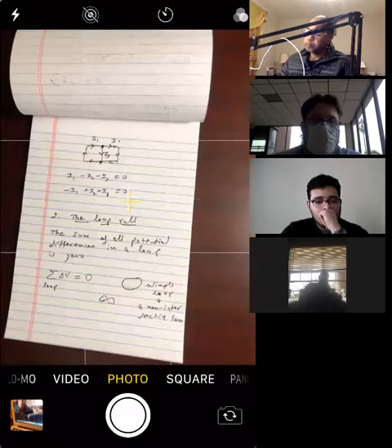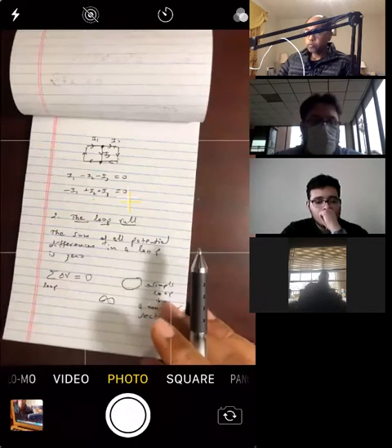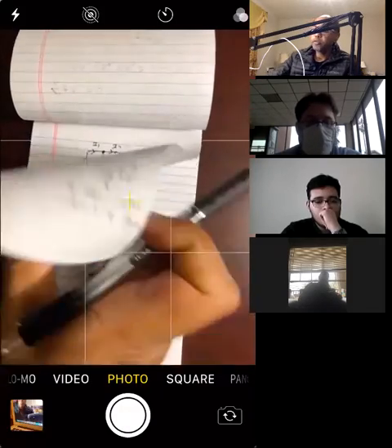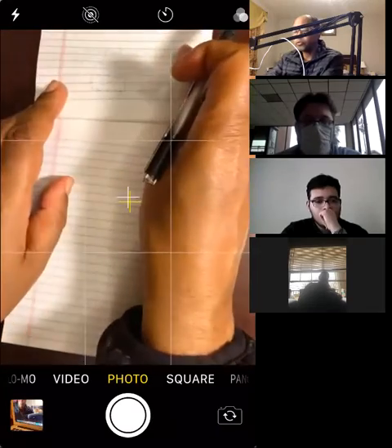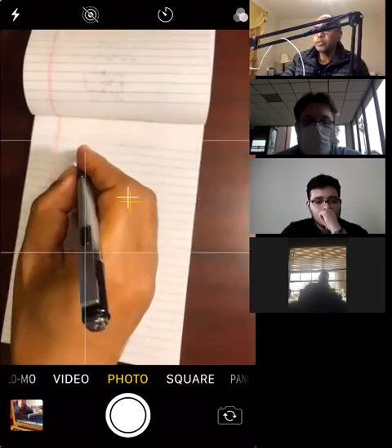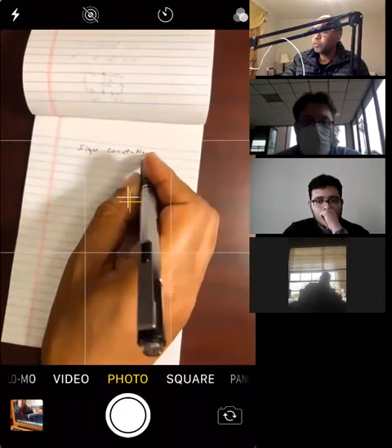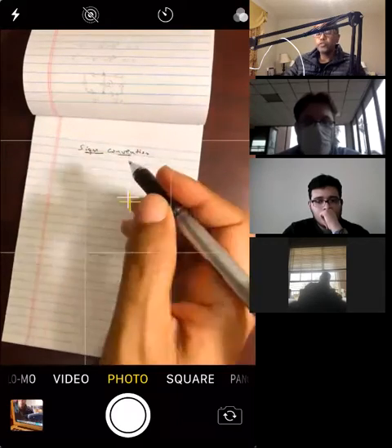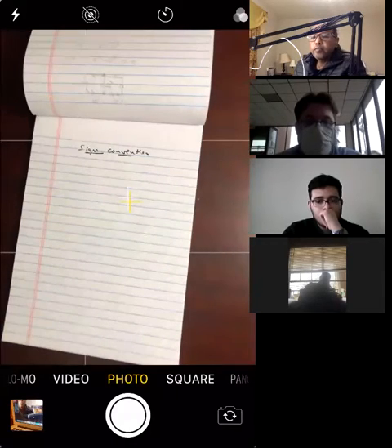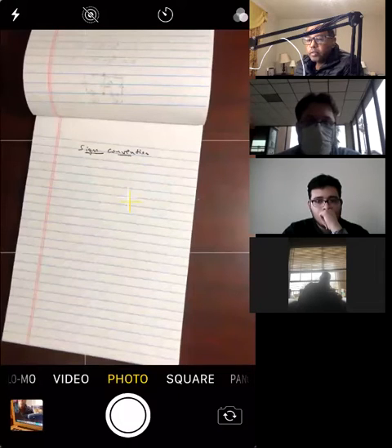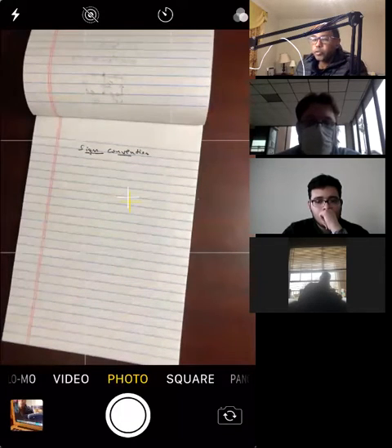Now, this is a very simple equation, but we have to be careful with the signs. So let's look at the sign convention, that is, when to make them positive and when to make them negative. As you know, there are two kinds of potential differences in a circuit. You've got devices that convert non-electrical energy to electrical energy, the source, just like a battery. And you've got devices that convert electrical energy to something else, that's a resistor. So we're going to have two different conventions for both of them.